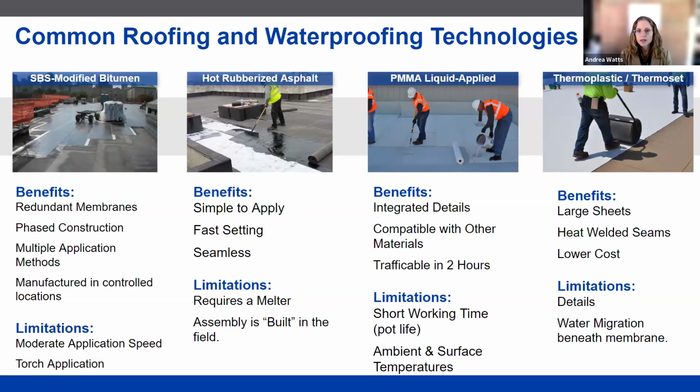It's also compatible with a variety of other substrates, including certain PVC formulations. So depending on what we're doing, if we're doing different sections of our roof in different ways, we do have the opportunity to mix and match technologies if needed when we're using the fluid applied.